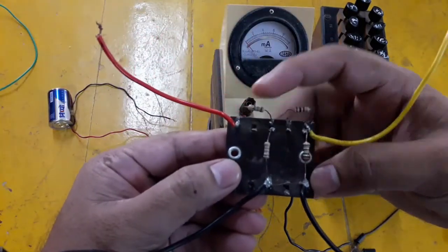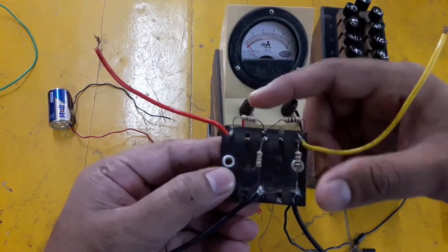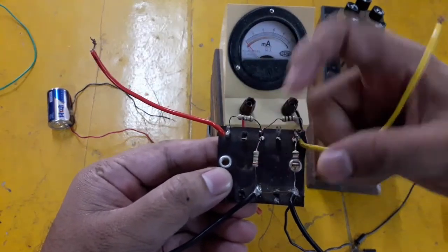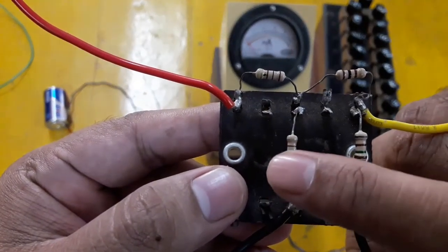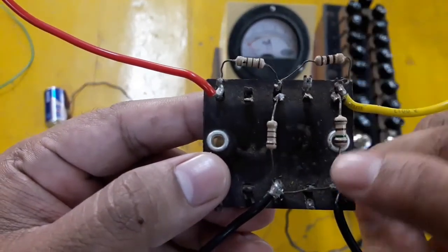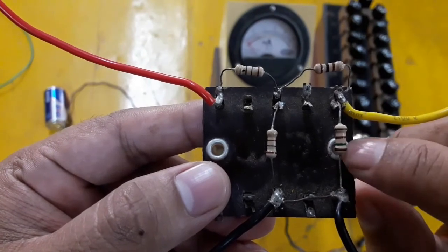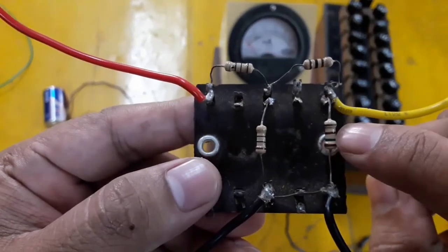Here we have the same circuit given to you. As you can see, there's a resistance 1 here, 2, 3, 4, and these are 100, 100 and 100 ohms, and this is 150 ohms. If you want, you can even use the color codes: brown, black, brown for these three, and brown, green, brown for this one. So this is 100 ohms and this is 150 ohms.